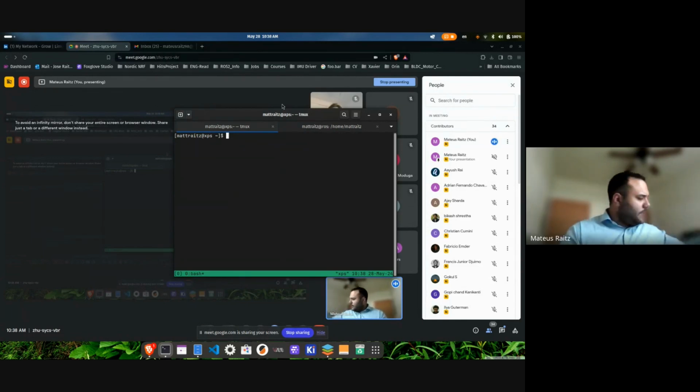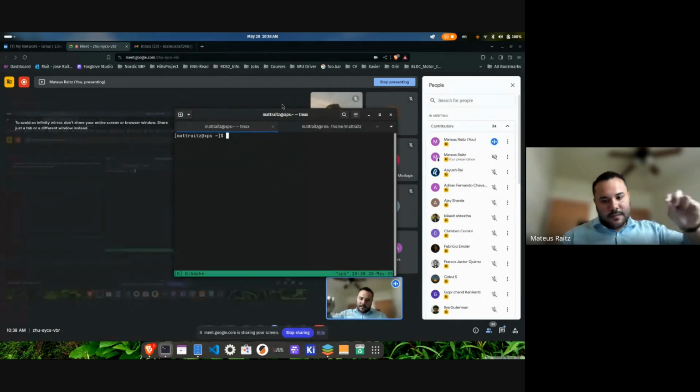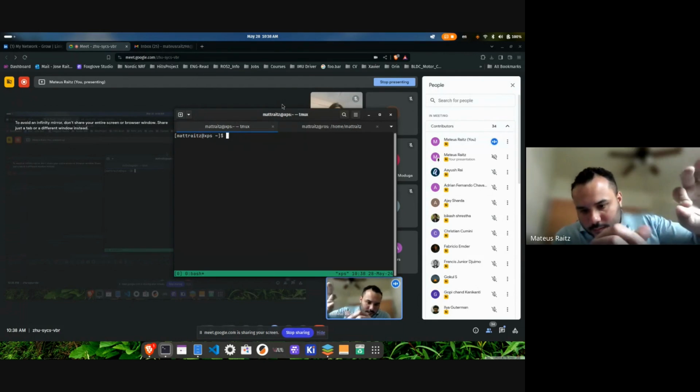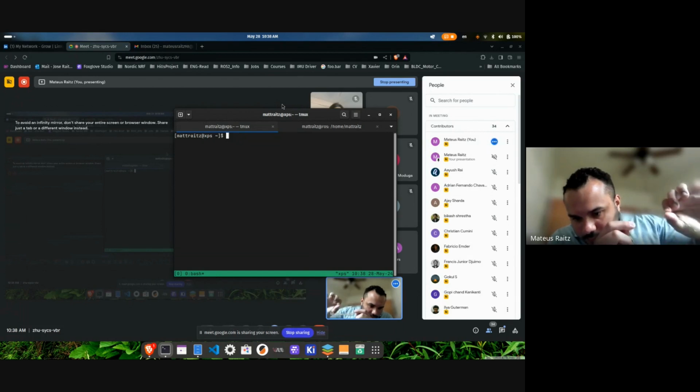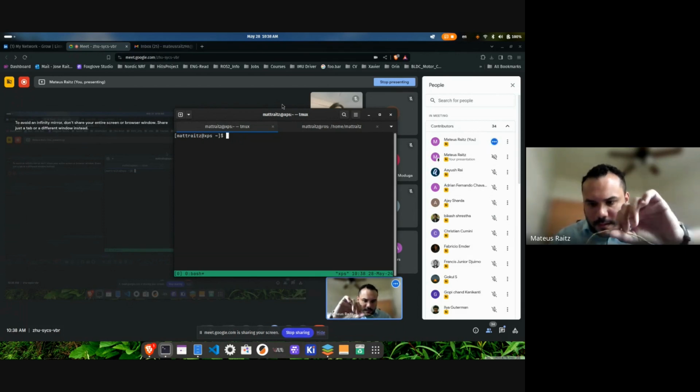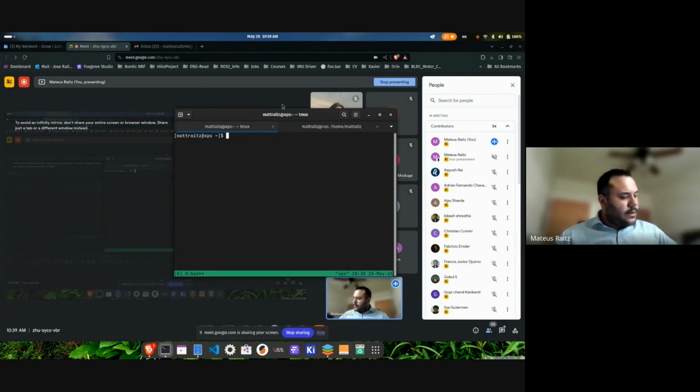So we can just launch micro-ROS through this. This STM32 is connected through CAN. It's blurring the cable. So here, this is the twisted pair cable used for CAN. It has an impedance of 120 ohms. Then you terminate each side with 120 ohm resistors. If you can see it, it's connected to my CAN probe to my computer.